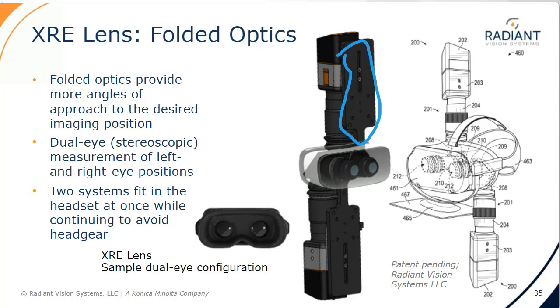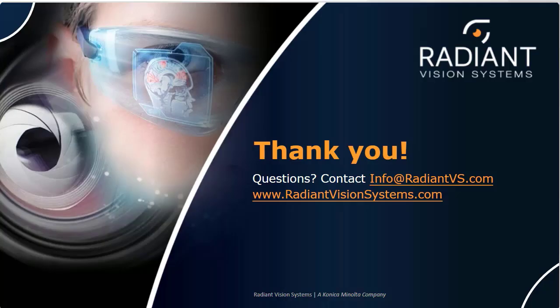It's a really good question, and it's not always easy to answer. The MTF of the imaging system itself needs to be taken into account, and we do have that characterized, and we can share that on a need-to-know basis if you want to reach out further. But as a general rule, for imaging systems and measuring displays, you typically want to have 2 or 3 pixel size squares per pixel. Again, it really depends on the application. Let's say you're looking for dead pixels or stuck pixels, or you want to do something like demura where you're trying to correct all of the display pixels so that they become uniform. Obviously, the higher the resolution you have, the better. But often we're able to get away with a 2 by 2 sensor pixels per display pixel.